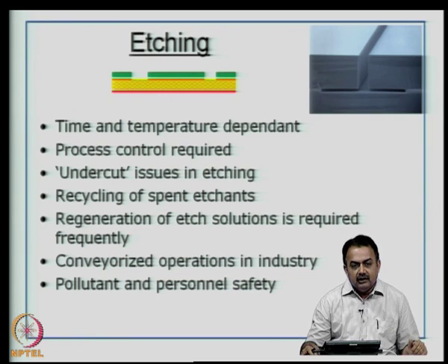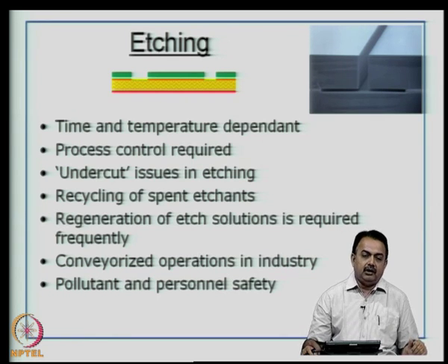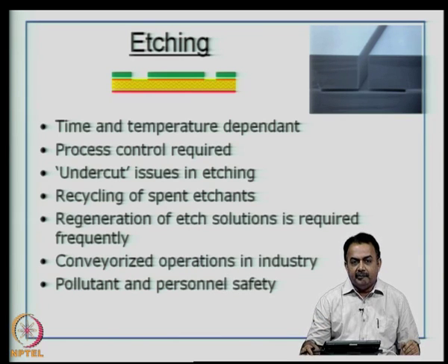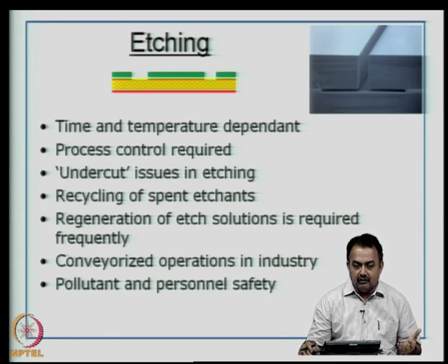So, the next point is regeneration of etch solutions, which is required frequently, because when you make up an etch solution, the concentration of the basic etchant ions or the etchant free radicals or whatever is generated based on the etchant, it has to be regenerated. Now, the rate of etching comes down slowly as you progress using the same etchant. Therefore, you need to monitor regularly the concentration of the copper that goes into the solution, because the basic reaction of an etchant with the copper surface on the PCB is that the copper has to dissolve into the etchant.